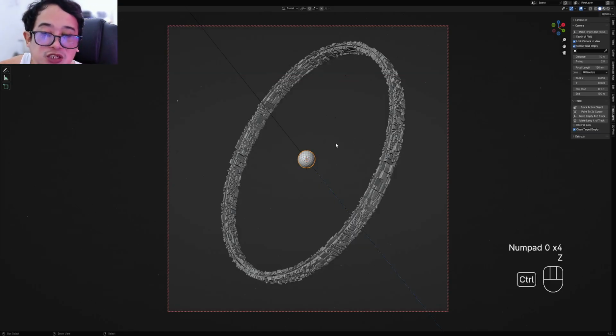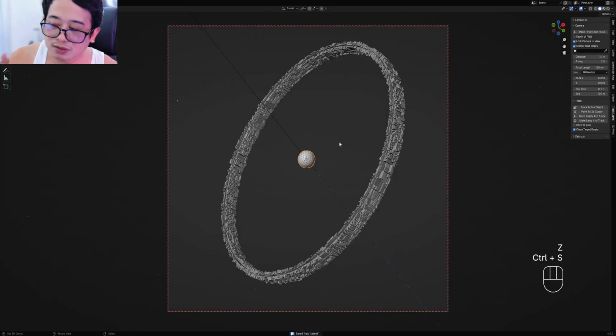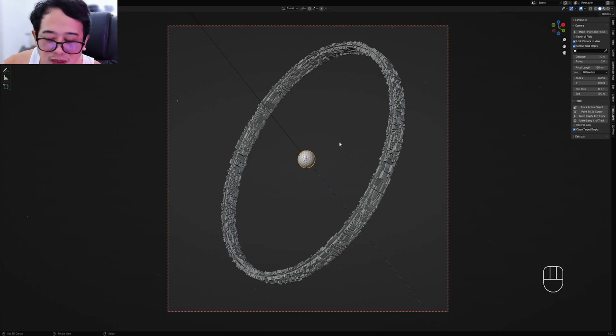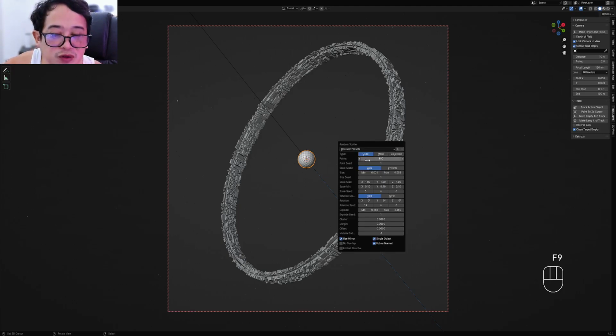You can scatter shapes, of course, but be sure that they're pretty light. The higher the resolution of the scatter object, the fewer points you should use, because using too many points with high resolution objects can slow down or crash Blender.